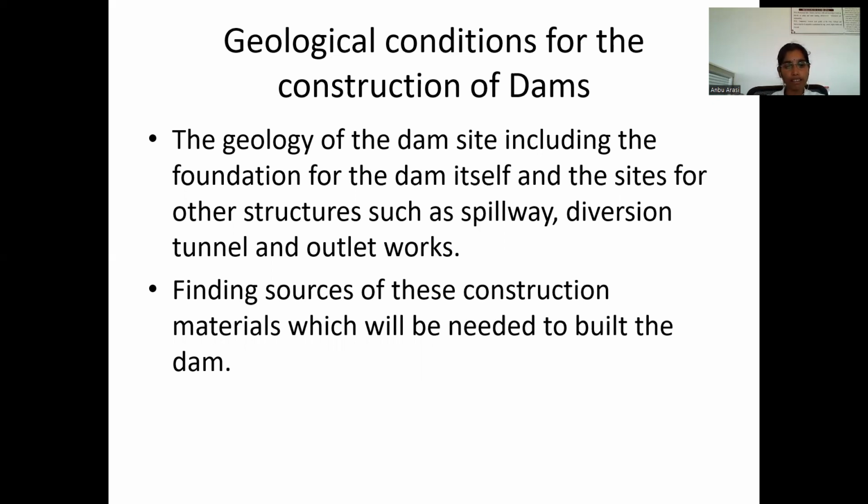Questions often asked here include whether the storage area is watertight or there are areas of cavernous limestone which might lead to the dam not retaining water, and whether landslides into the reservoir are possible, which might cause a wave of water to be pushed over the top of the dam. Finding sources of the construction materials which will be needed to build the dam.